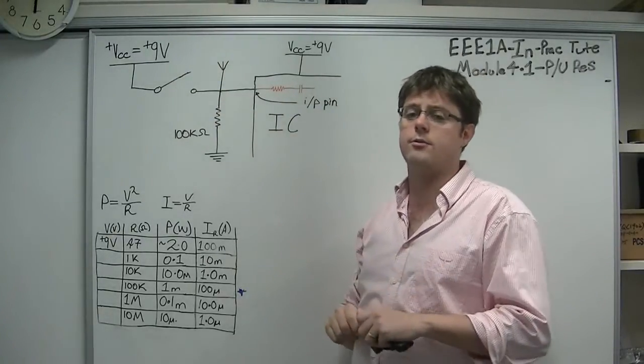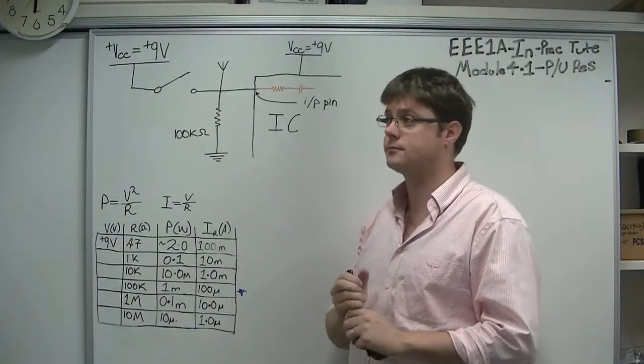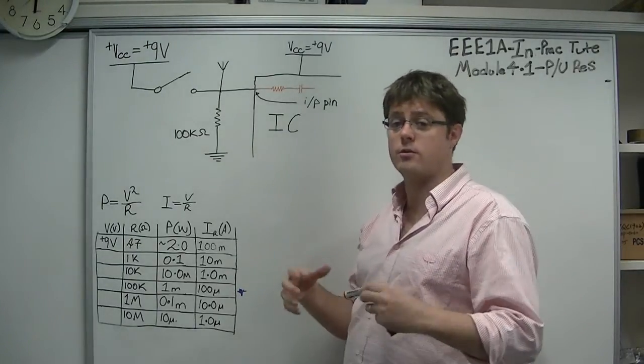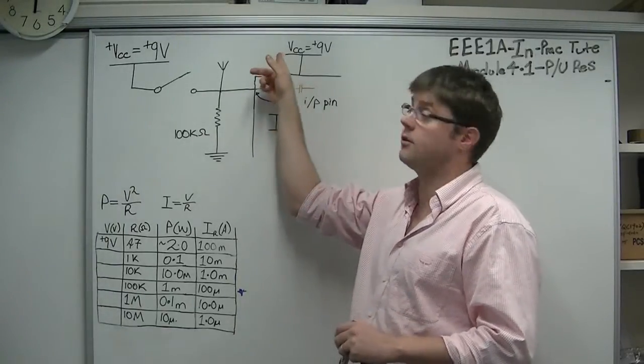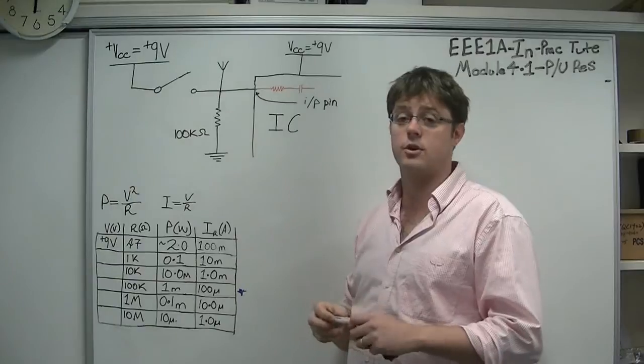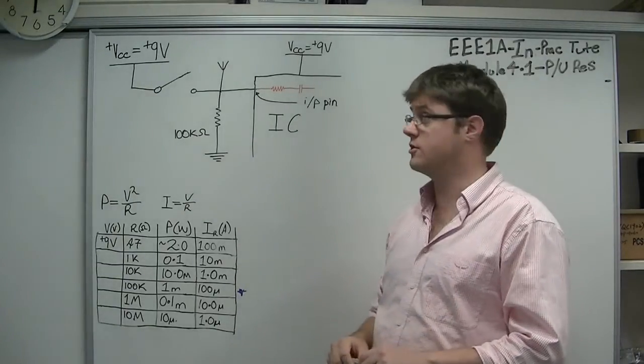So you're not going to have a hard digital value set. In fact, quite often you can even get an input voltage on this device that's going to be higher than the rail voltage, and hence you might end up cooking the IC. All badness. So we want to avoid that situation.